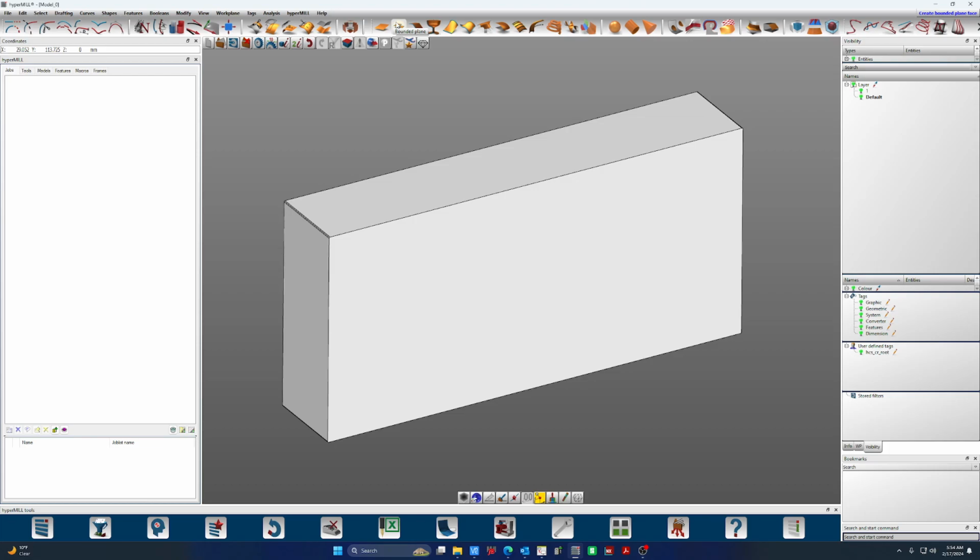Bounded plane. Whereas a plane, we're just going to create somewhere in 3D space, usually parallel or perpendicular to our work coordinate system, our gnomon, our active work plane, a bounded plane is actually driven from geometry. Now, all of the geometry for a bounded plane needs to be planar for it to work correctly.